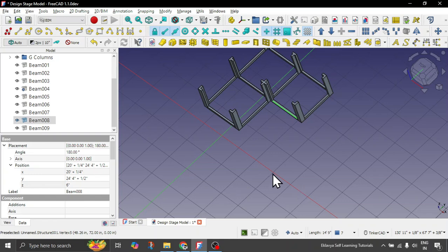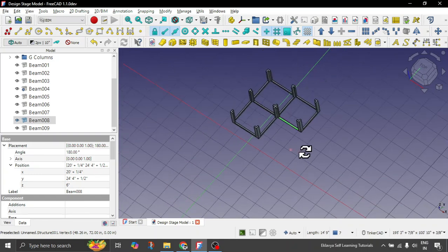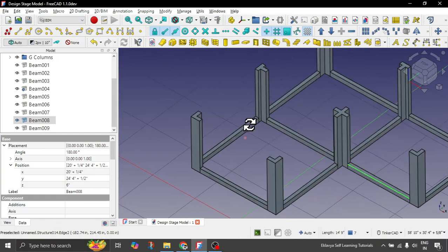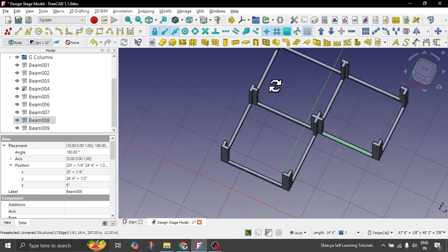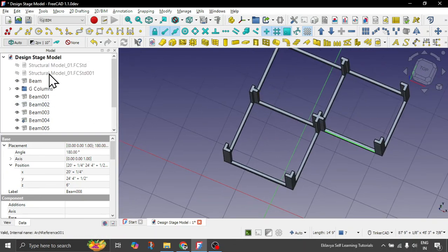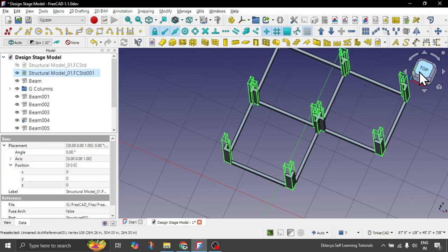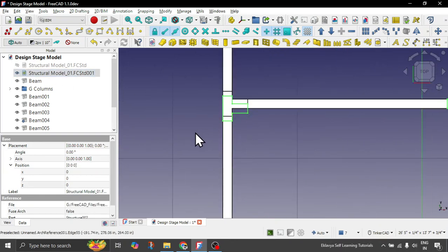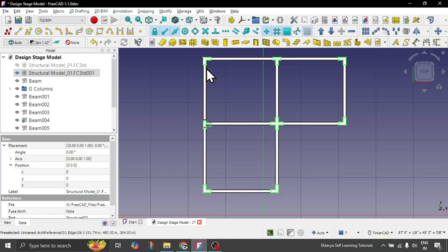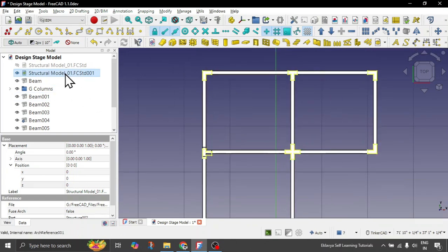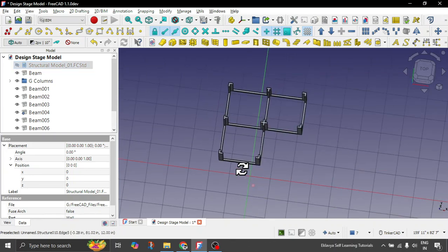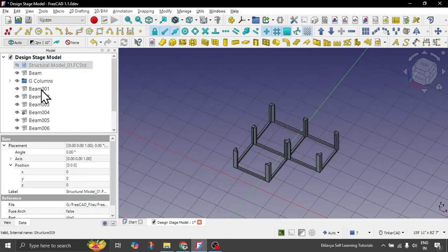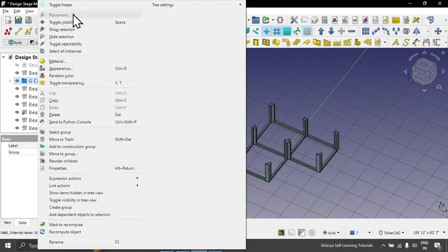Very well. We'll save the model, right, just for reference. So this is a kind of plinth level model that you have now created for your reference, right guys? If in case you want, this was the reference for the columns, right? So this was the deflection that we have. So now if in case you want, you can delete this reference by simply clicking on delete. Cool. Boundary one will still use. Okay, so this we have created. Now let's create group for beams also.